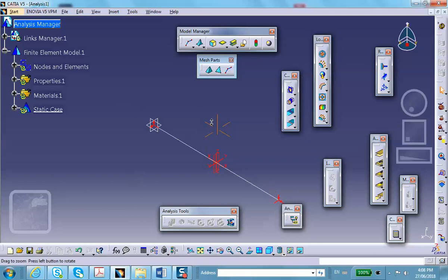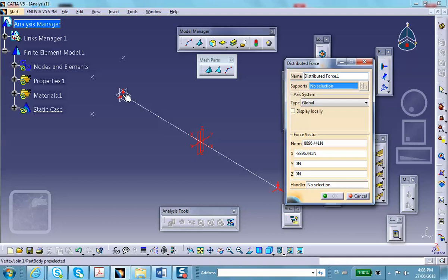All right, now what about the load? The load is at this end, so you apply a force at that point. Let's say the original load applied was, hypothetically, 1,000 pounds, okay? But because you're using symmetry, half of that is being applied to the piece that we're modeling.